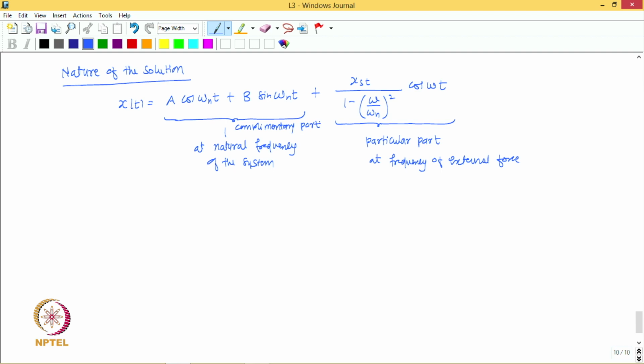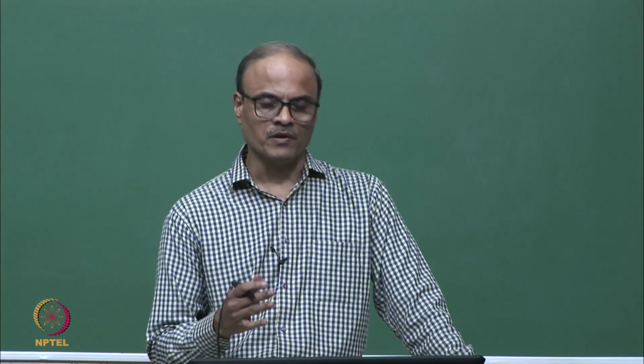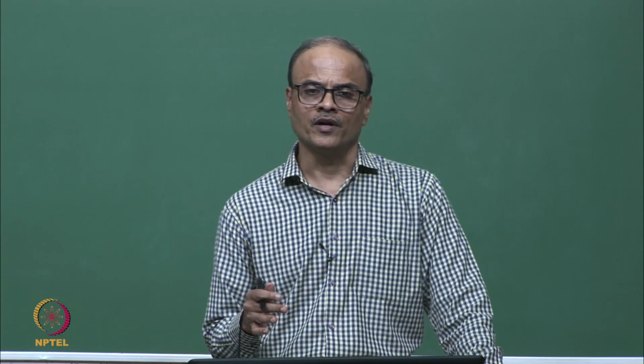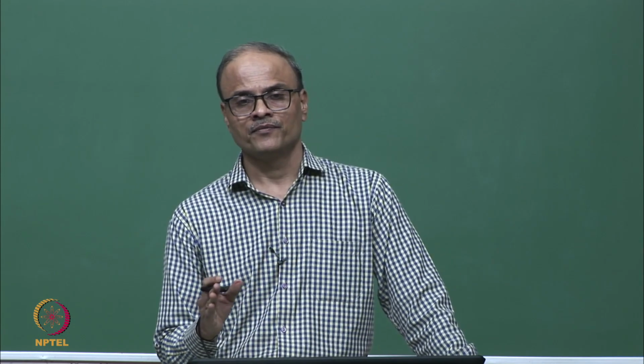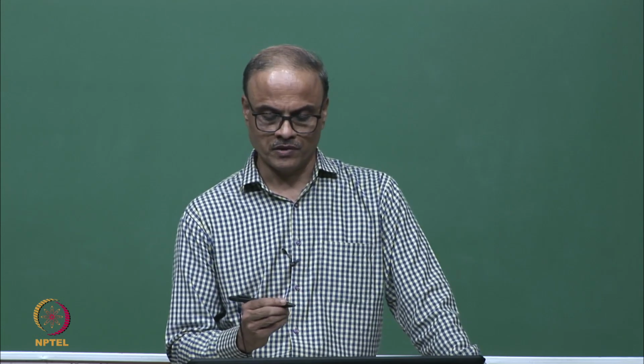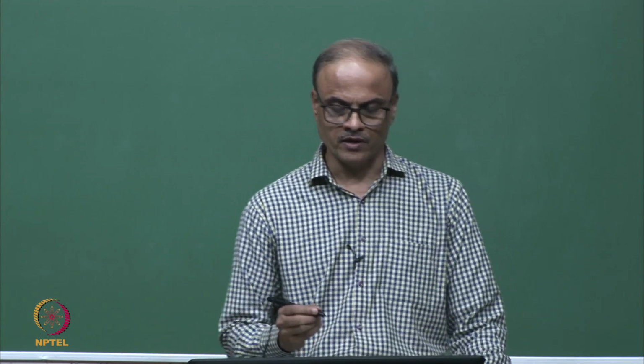So, that is I think the one important observation here. It consists of two parts, complementary part and particular part. Complementary part occurs at the natural frequency of the system, the particular part occurs at the frequency of the external force. As we will see later, complementary part is also referred to as transient part, because if damping is incorporated, this part will have its amplitude decaying with time, and hence it is also referred to as transient part. That we will however see when we take damping into account.